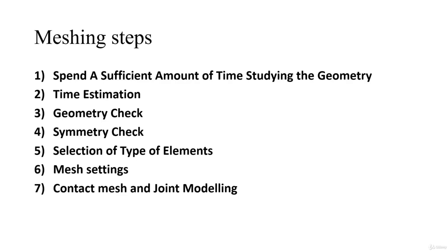So you need to study the geometry, and once you study the geometry, you need to estimate the time. You need to estimate the time of generation of the mesh as well as the time to solve the particular problem, and you also need to keep in mind what accuracy is required. So depending on the accuracy required, you need to perform the time estimation. Then coming to the third step, we need to check the geometry. Once we import the geometry from other CAD systems, we need to check whether any losses were created during the transfer process, or whether any data loss has occurred.